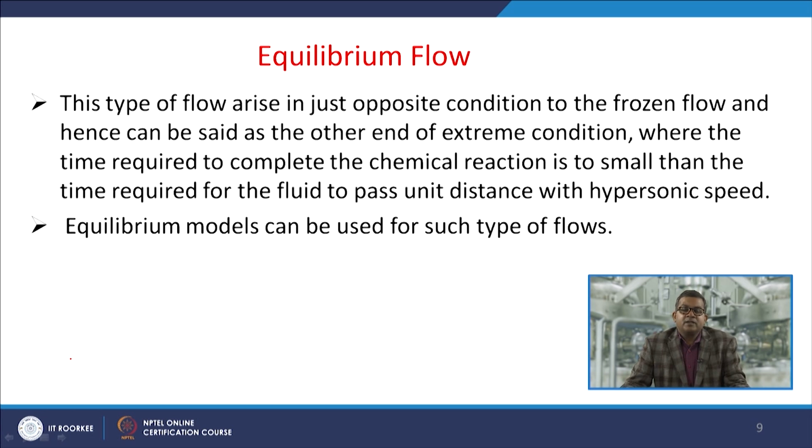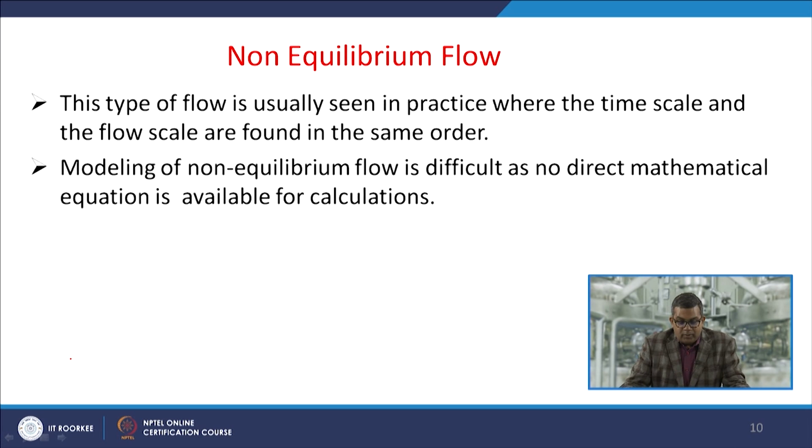Then we have to consider equilibrium flow. This type of flow arises in the just opposite condition to frozen flow, and can be said to be the other end of the extreme, where the time required to complete the chemical reaction is too small compared to the time required for the fluid to pass unit distance at hypersonic speed. So the equilibrium model can be used for such flow.